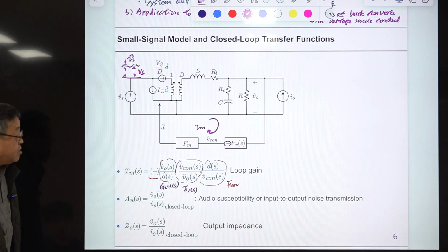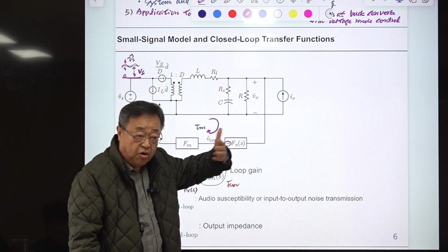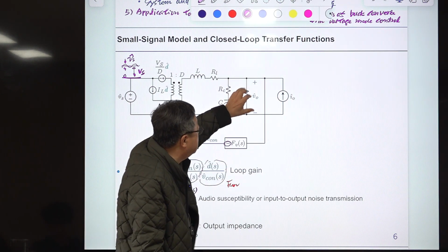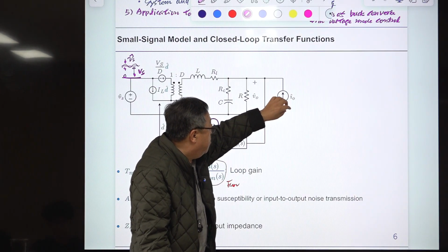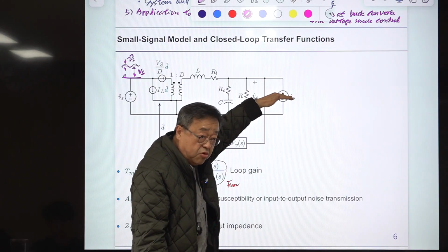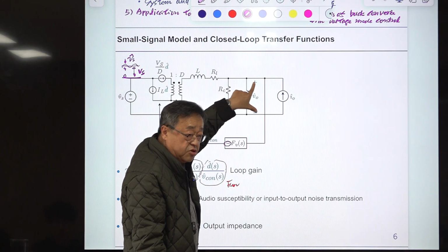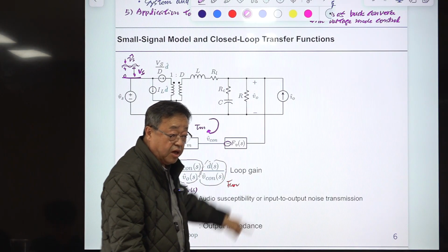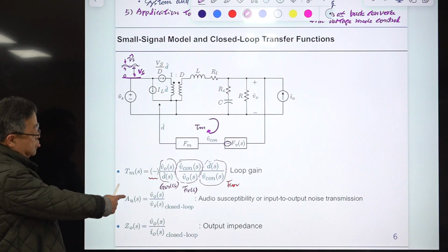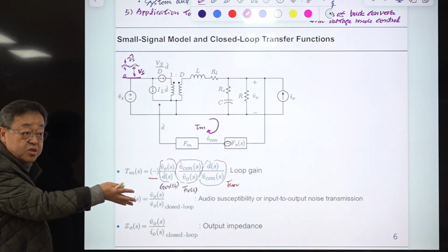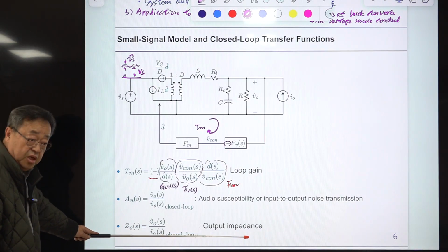So if there is some noise coming in the output current, or some disturbance is changing, or this noise current is modulated from a fixed value in a sinusoidal fashion, then the output will contain a sinusoidal component at the same frequency. The characteristic of that is called output impedance. You use output impedance many times in an audio amplifier or any amplifier. This is a very important parameter.